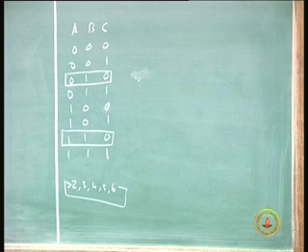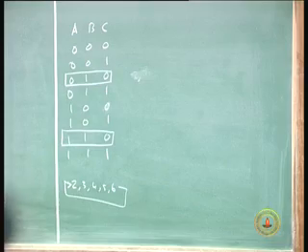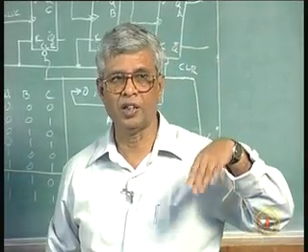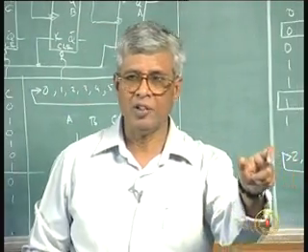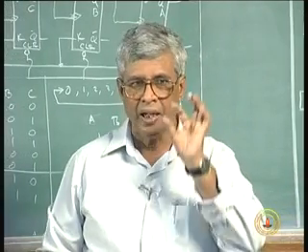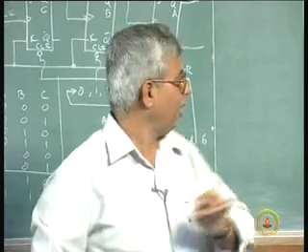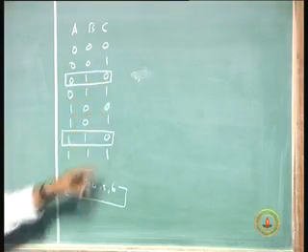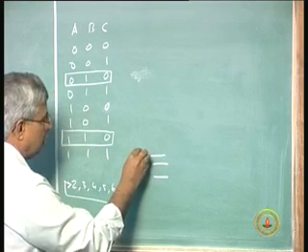So, again I will do the same thing. I look at 6, I have to complete. So, I cannot detect when the flip flops reach the count of 6. I have to wait for count 7 to come up, because 6 has to be completely allowed. So, when count 7 comes up, which is 111, I detect that and now clear the flip flops. In this case, I will preset this flip flop and clear these 2 flip flops, correct. So, I will get the count 111, this is ABC.